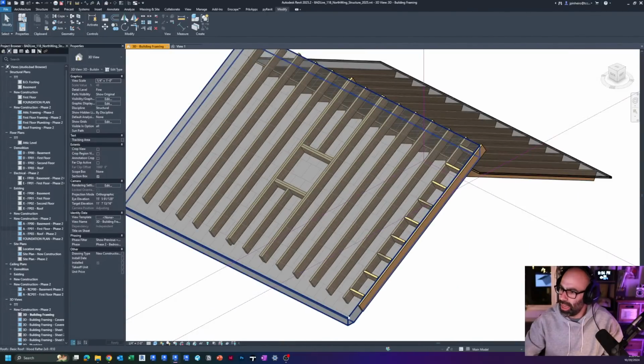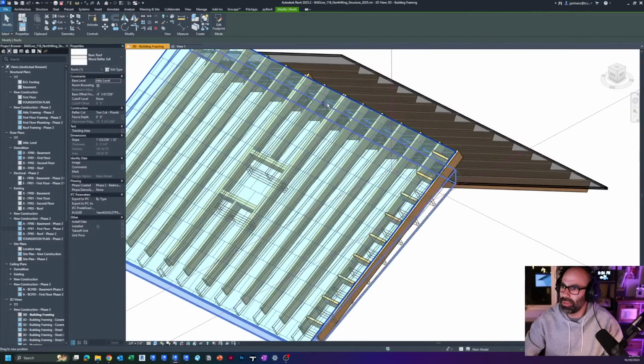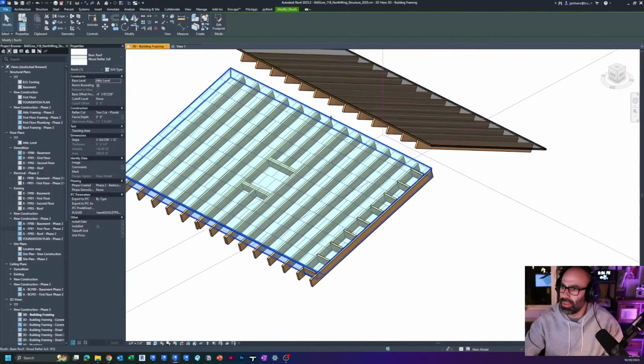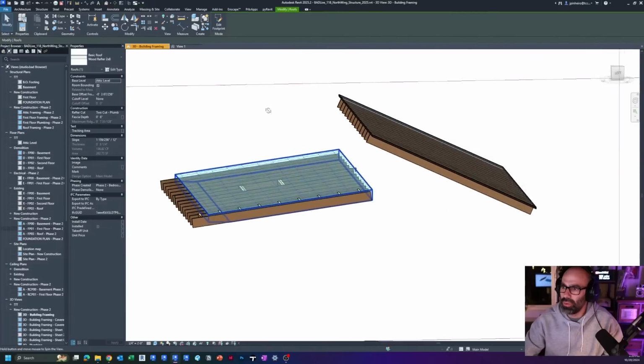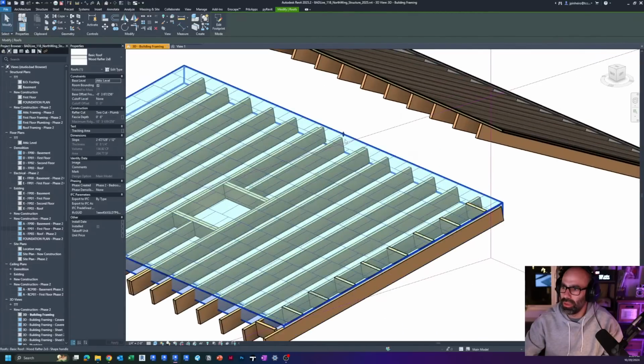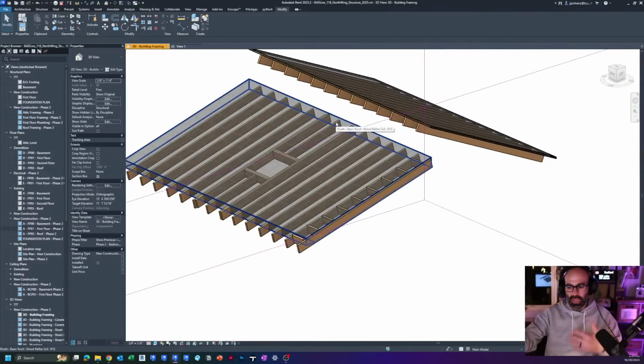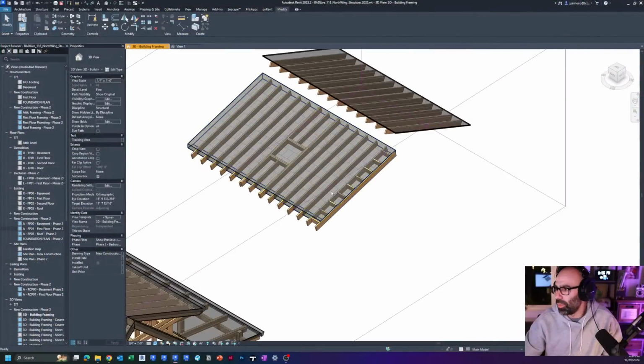Okay, but again, because I copied it from the beam system, look at this. It's flexing with it. See that? And so because you start with this host and everything's hosted to the roof edge, it makes it super simple to be able to make things like openings and double studs and ridges and ledgers and whatever we want to talk about from there.